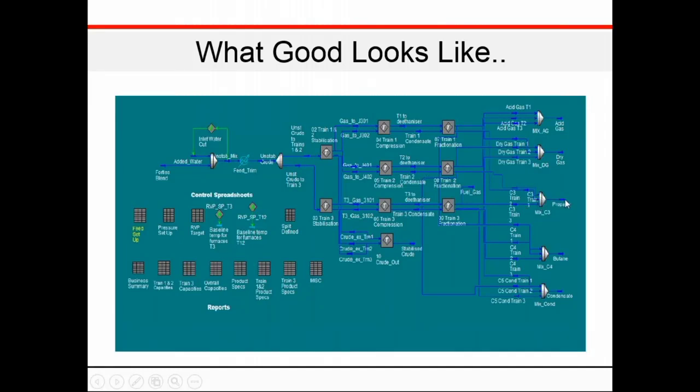We have propane at this collection, butane at this collection, and condensate at this collection. This is just trying to show you an example of what happens in crude oil in the fractional distillation process. All these T's are the trays inside the fractional distillation column. So we also have to simulate them and bring them out like this.